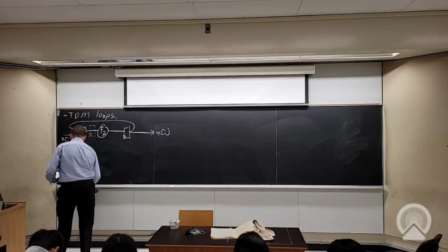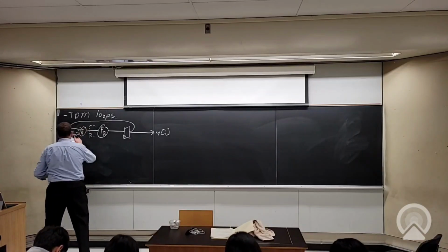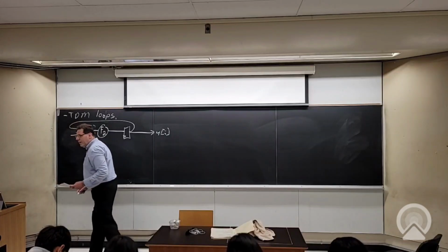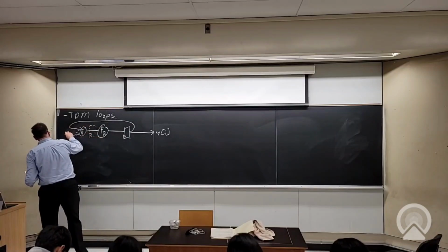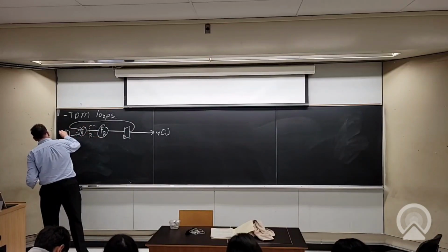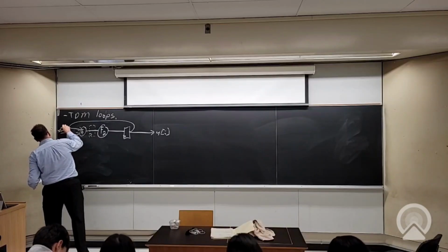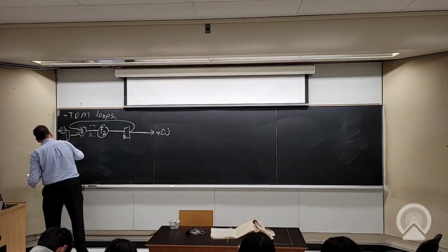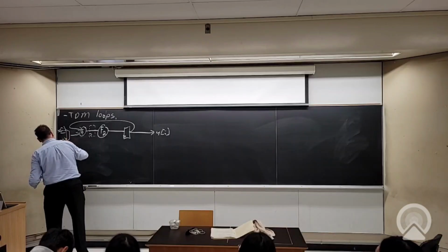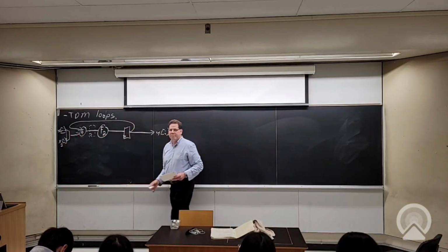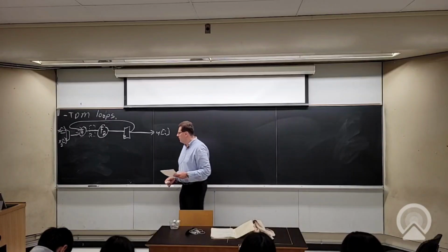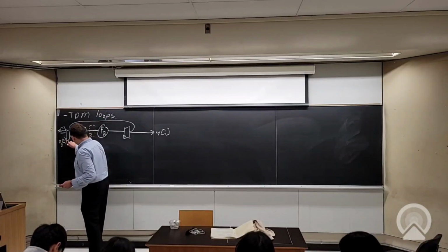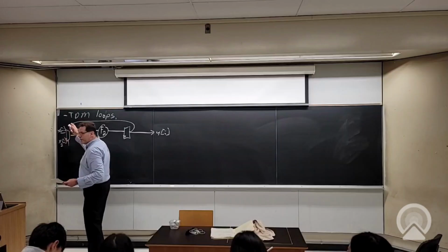So what I do, let me erase this. Okay, so if I put this register in, I have to put another bit of circuitry in. So I can put in two streams of data. Let's call them x1 and x2. Okay, so those are two totally independent streams of data. Maybe it's a wireless system again. They're coming from two different antennas. And what this is now doing is basically every cycle, I'm going to flip between the two inputs.